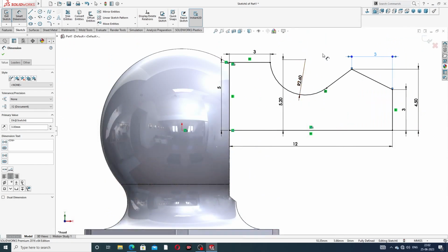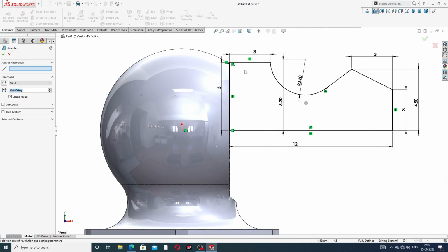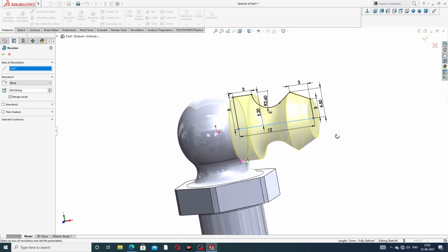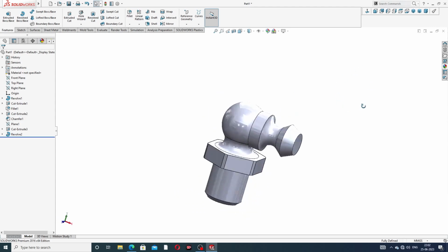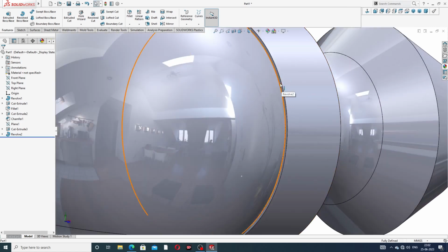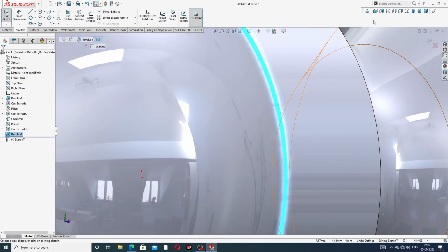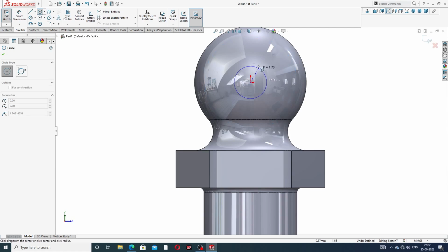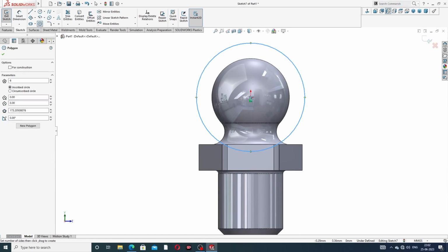Okay, and click revolve boss base, and click this. All is perfect. Looking here, click OK. But some points are very important. This face, sketch here, sketch normal, drawing a hexagon. Draw a big circle, and also a hexagon.